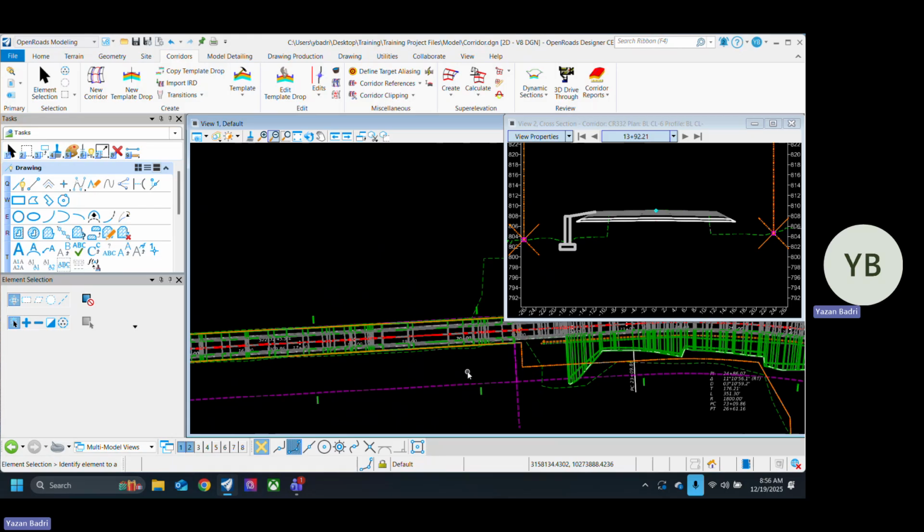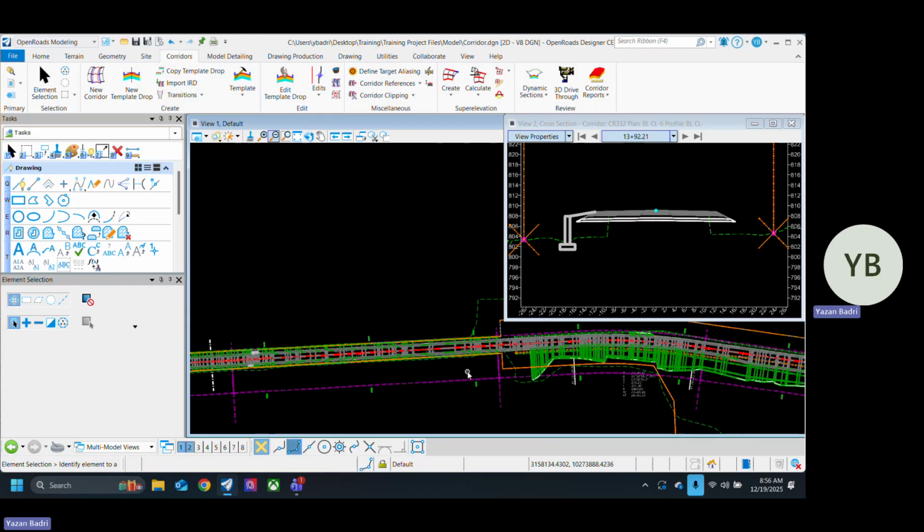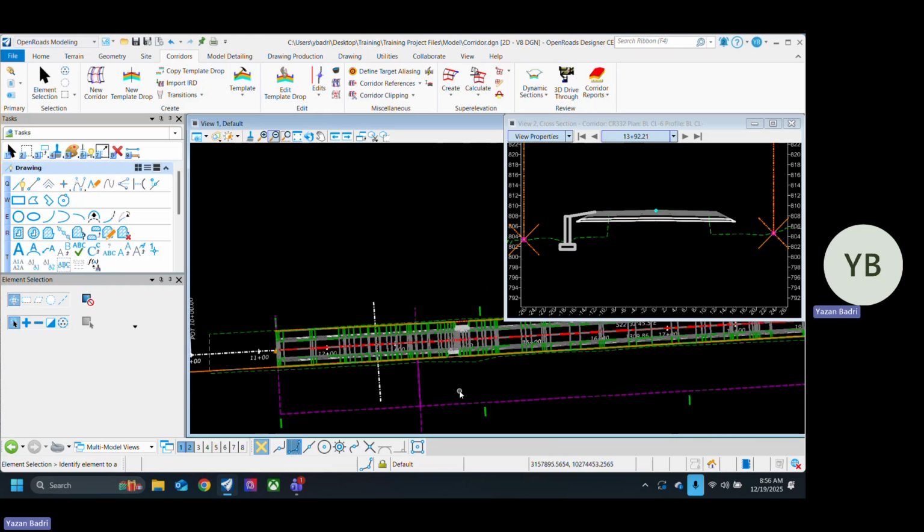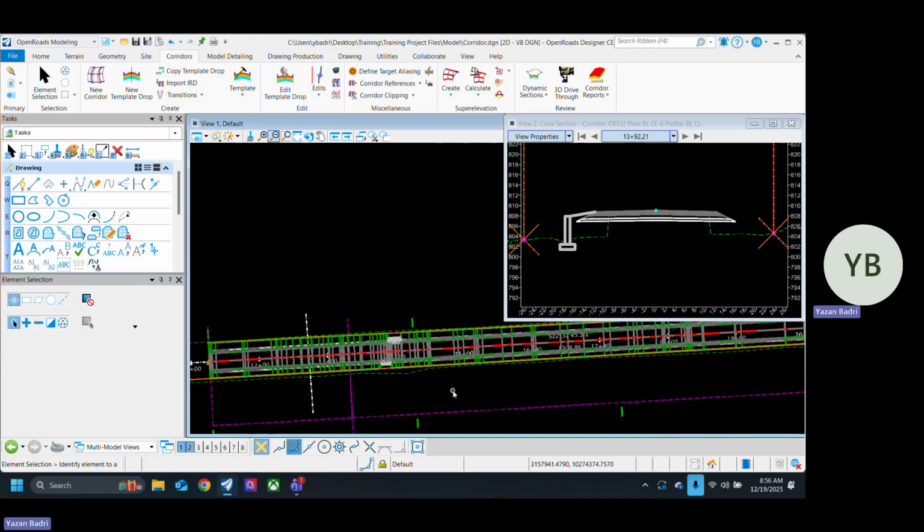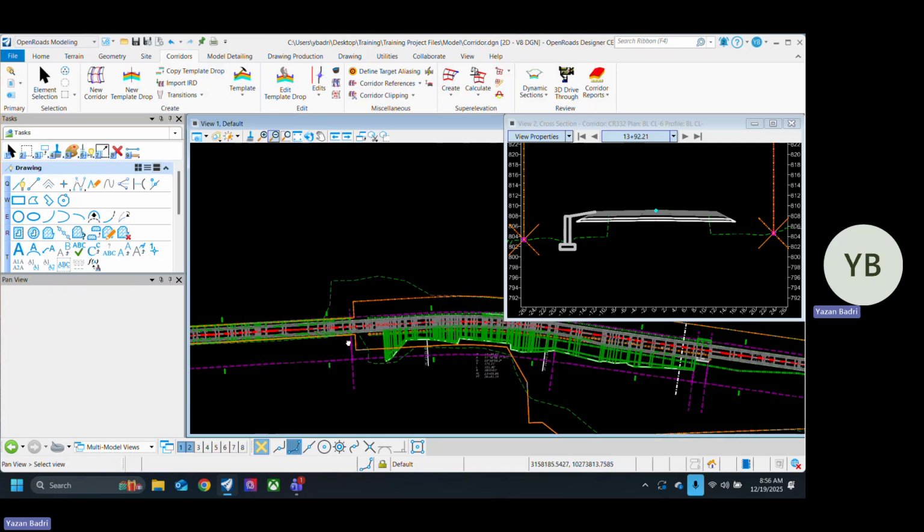If you want a smoother model, something fast that wouldn't really be slow to work with, you'll try to avoid using too many point controls. I mean, you have to use them in some places, but you try to avoid some if you can. So number one, most demanding is point control. Two is parametric. Three is display rule.